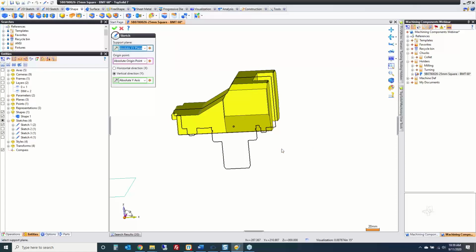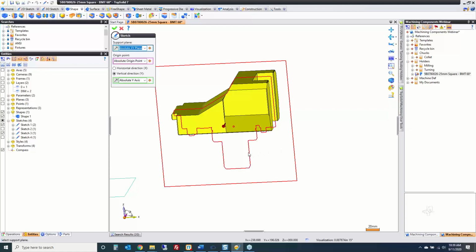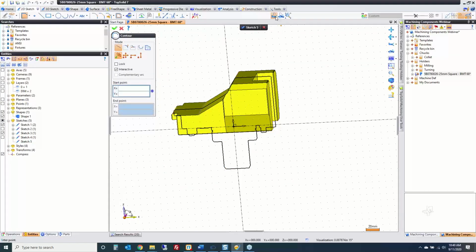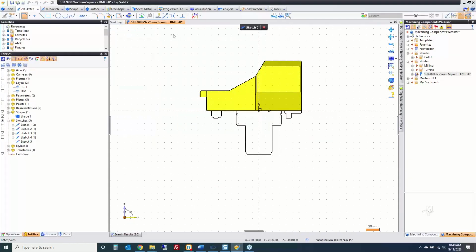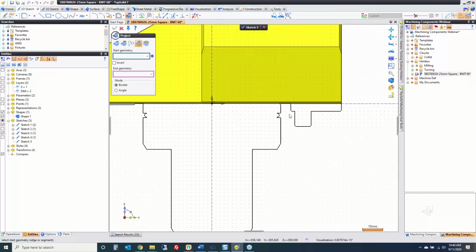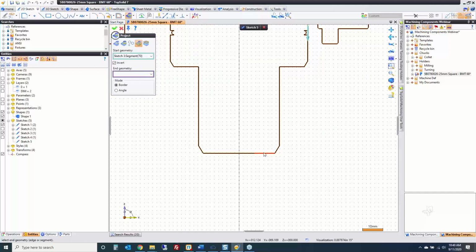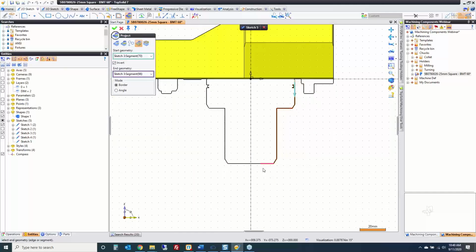So what I'm going to do here is I'm going to define a new sketch. I want the sketch to be on the same plane as that curve. And I want the origin point of the sketch to be my origin point of my curve. This simplifies everything a lot, okay? And now I'm going to start by selecting some things here. Let's do path between two edges and we'll choose border, okay? So if I select this, going down that way, and I go to here, that's going to grab all of those curves. Perfect. I'm going to grab this, and why not that edge as well, okay?